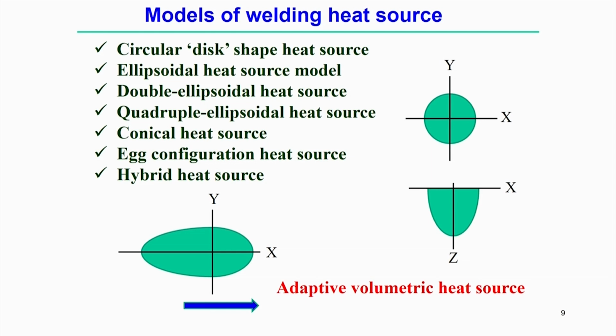In that case, it is not necessarily exactly symmetric with respect to one plane. Here comes the non-symmetric nature of the heat distribution as well as the geometric shape of the weld pool, since there is some finite velocity in one specific direction. In that case it is generally called linear welding.